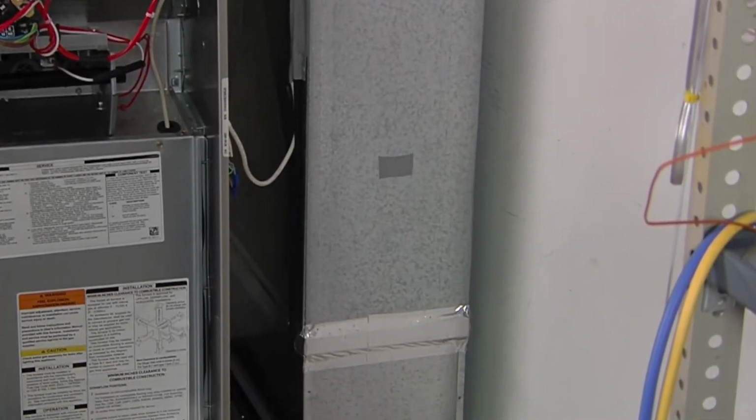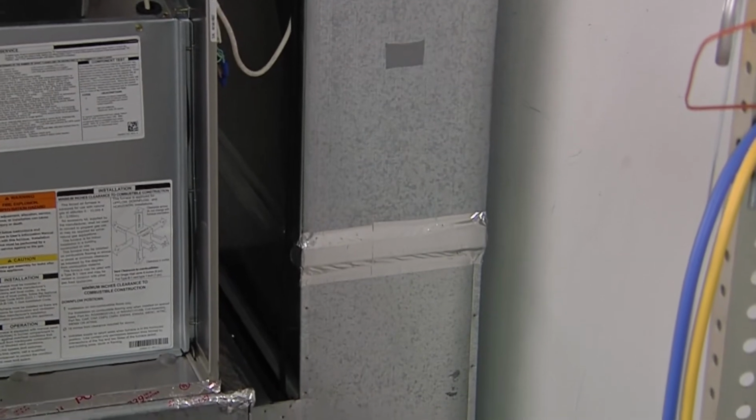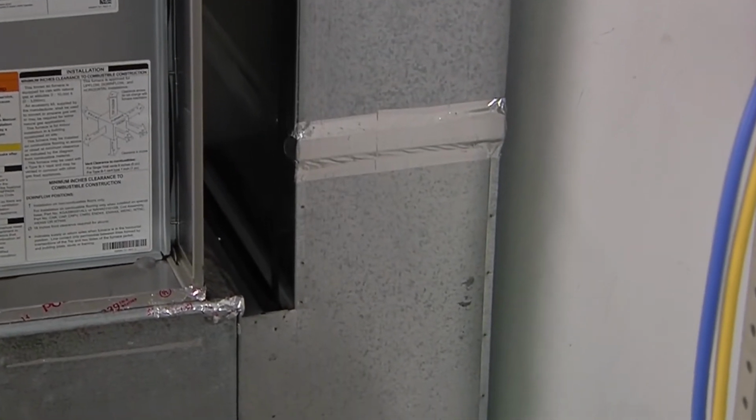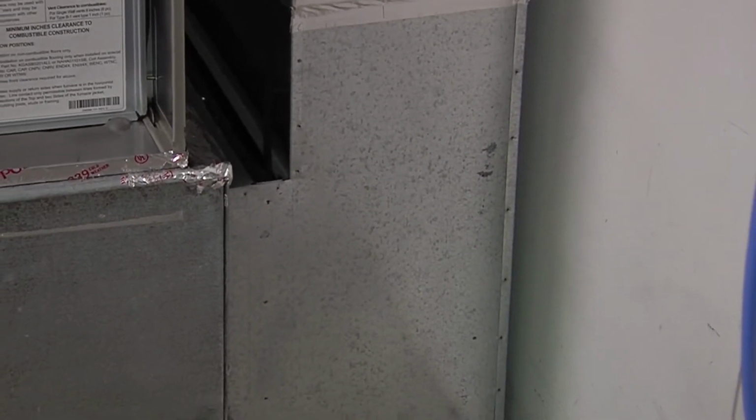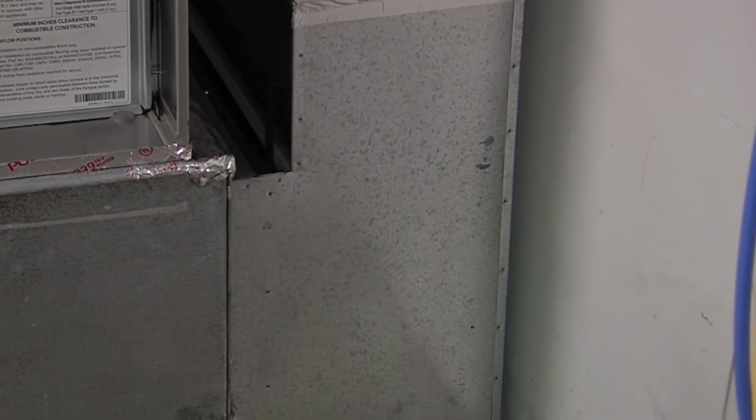It is important to take the velocity readings in a straight section of duct before any elbows or takeoffs. The ideal location in many furnaces and fan coils is the return air duct right before the return air boot. If the return is a box connected to the furnace with branch returns, you can measure each branch return and add the results together to achieve the total CFM.